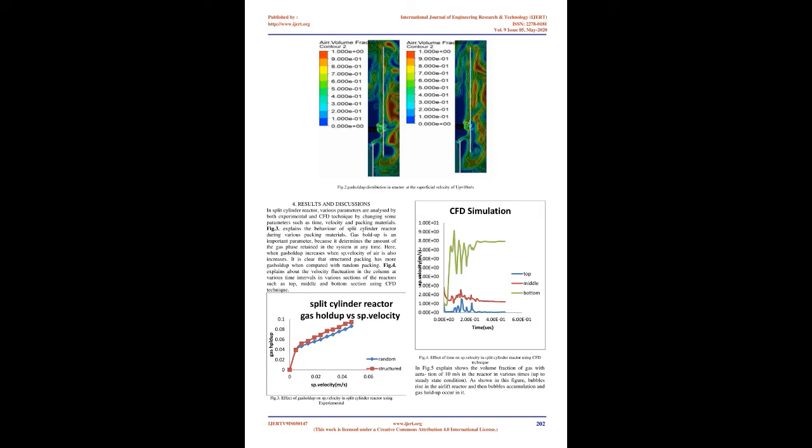Initially, the column is filled with a textile effluent up to a certain level in the column. Note down that height as the initial reading of liquid height. Then, the stirrer is allowed to rotate at 500 rpm constantly. At the same time, air is allowed to pass through the column at different airflow rates from the compressor. When the column attains the steady state, note down all the corresponding readings.